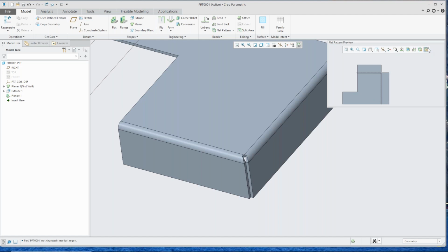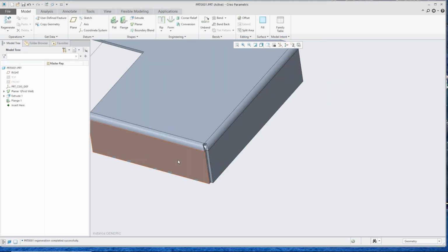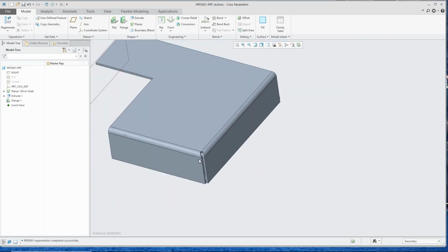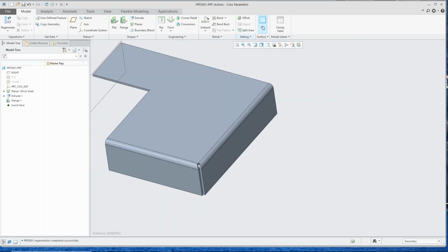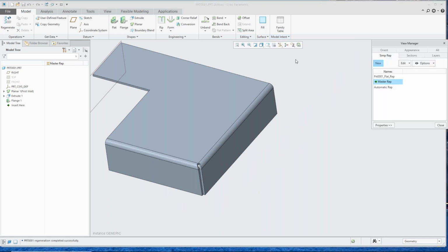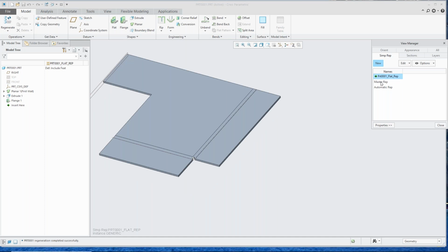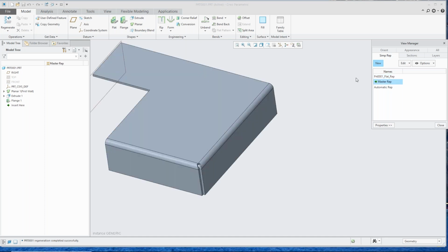Also, another thing that's been added: when it initially started out, you could align your subdivisional model or surfaces to a plane, and then you could align them to surfaces, and then you could make them tangent to surfaces. And now with Creo 5, we can make them G2 curvature continuous to any surfaces that they blend into.